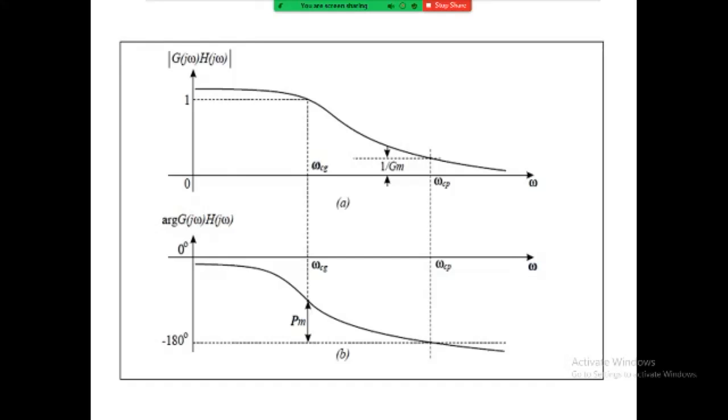Therefore, these frequency transfer functions are defined for sinusoidal input having all possible frequencies, that is, omega belongs to 0 to plus infinity. They are obtained from the above equations, the transfer functions for open loop and closed loop systems, by simply putting s equals j omega.